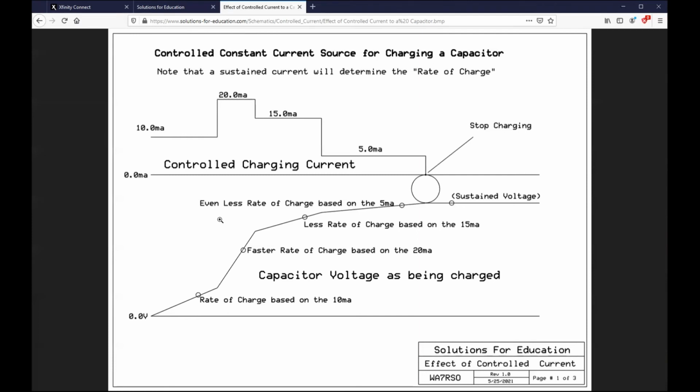Well, anyhow, I really hope that by going this route, by taking away from the normal voltage aspect and concentrating on controlled current maintained at a constant value, and look what it does. And you can do this with certain circuitry. As an example, in transistors, and we did this with tubes also, a grounded grid amplifier had the characteristic of maintaining a constant current. A common base configuration for a transistor has a very interesting characteristic. It's a constant current source.